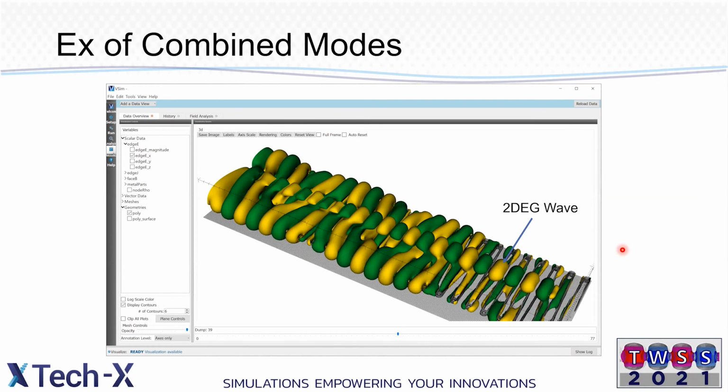It's Vsim. You can always make some really pretty waves. So here's a similar thing. You see the initial wave on the 2DEG, or on the meander line down here. And then you see the space charge wave up here. These are E-axial, so the electric field in the axial direction. You can actually see that the space charge wave is running a little bit ahead of that, or well, actually it's probably converting energy from one to the other.